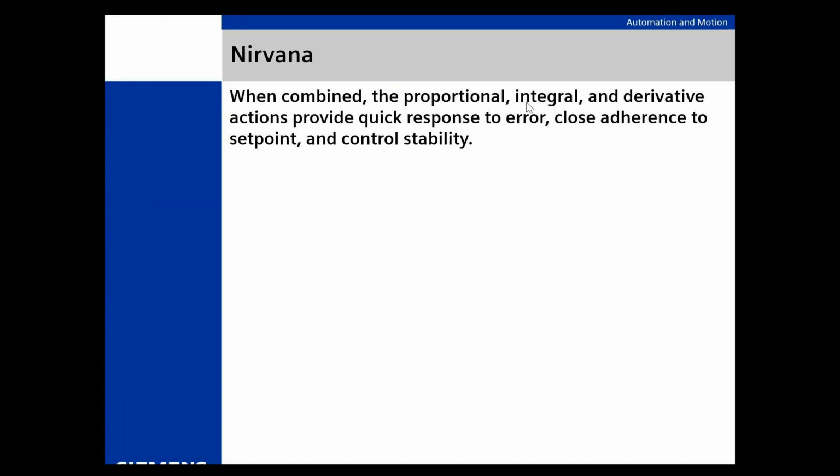If I auto-tune it 5 times and those numbers are radically different, that means the system is not repeatable. It's not going to auto-tune. There's just no way. You're back to PID. You're back to messing with it the old days like I had to do. Now, with that, I'll also say, if you've got a loop and it's running just fine, life's good, do yourself a favor, get in there and write down somewhere, keep the PID. Know what that is, because believe me, it's going to be in your best interest to know what that is, especially if you have to manually do this.